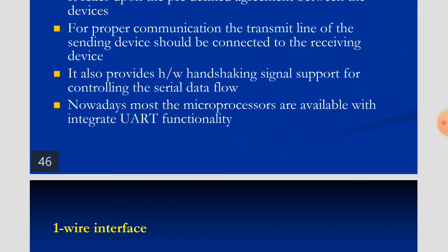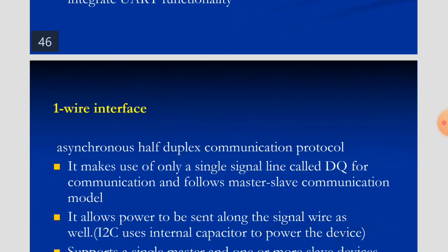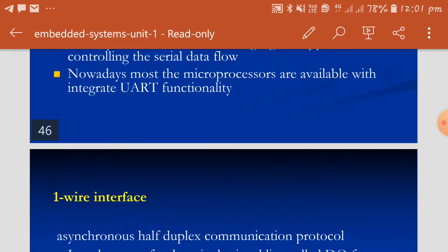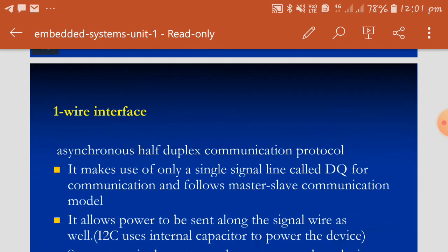After the end of the communication, it is going to send some stop bits that indicate our communication has ended. Like that, it is going to send some start and stop bits with the data. Nowadays most microprocessors are available with integrated UART functionality.